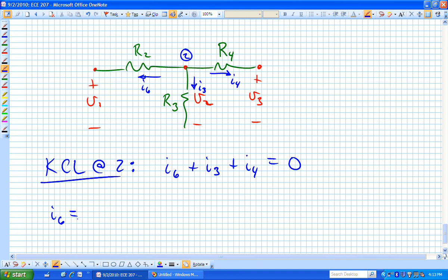Does that make sense? If you go back to what we did just before, we were trying to find I sub 2 going to the right. And that was, we look at where we are now, which was at V sub 1. We subtract the voltage where we're going, which was V sub 2, and divide it by R sub 2.